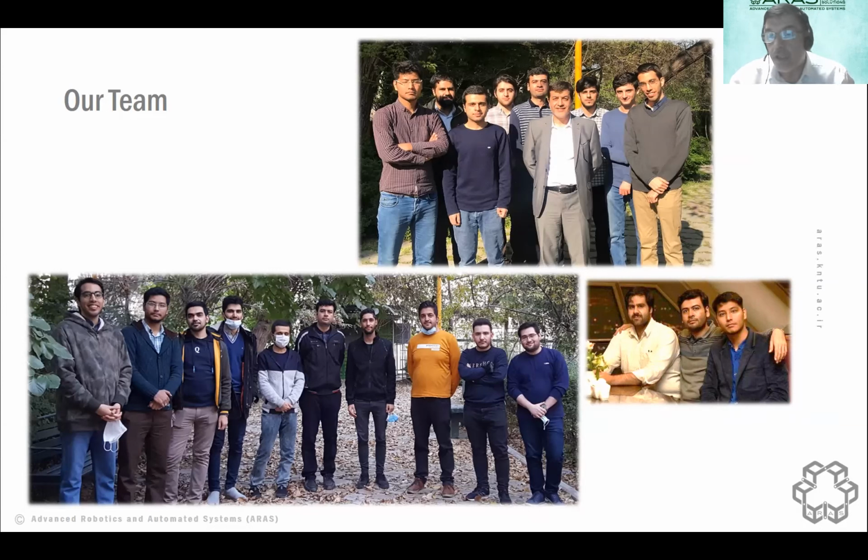And there are a lot of kinematic approaches to make sure within which workspace you can operate without singularity. So all the workspaces that I showed you are all singularity free. Not only singularity free, they are fully applicable by tensile forces.